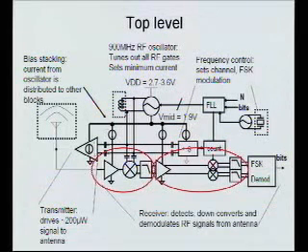How long does it take for them to drift out of sync usually? Crystal oscillators usually have an accuracy of about 50 parts per million or something. That means my estimate of a second will be different from your estimate by 50 parts per million. So a couple microseconds.